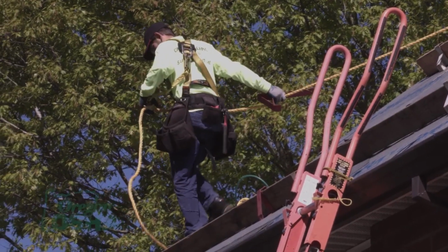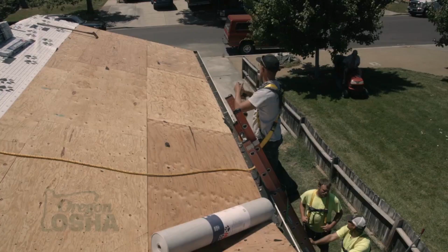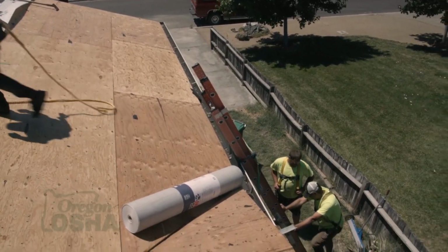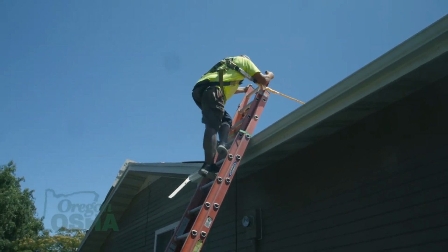On the roof, if it has a pitch to it, like a 5/12 or 6/12, you can typically step onto the roof okay. When you get up into 7, 8, and 10/12 pitch roofs, you typically want to have a slide guard or something to step onto so that you can be safely up on the roof and work from there. But on most residential houses, you set your ladder up, secure it to the building, and make sure your ladder extends 3 feet beyond the eave so that you're in compliance. It also gives you something to hold on to when you're stepping onto the roof or off the roof onto the ladder. What I've seen is that most falls happen on that step getting off the roof onto the ladder. For some reason, people are just not very comfortable stepping that way, so making sure the ladder is secured is really critical.